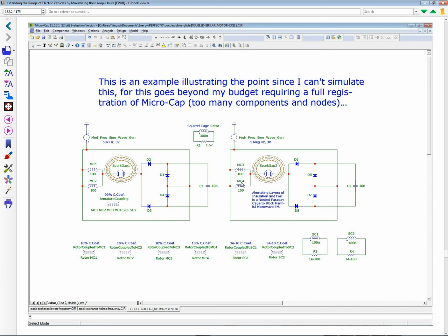Now we do take the wires off, and rather than do a bifilar, we do a quadrifilar, but we only unite them in pairs so that they're two sets of circular rings wound back upon that bobbin. Or, in the alternative, we have two bobbins on opposite sides of the armature, and one is bifilar and the other is bifilar, depending, I don't know.